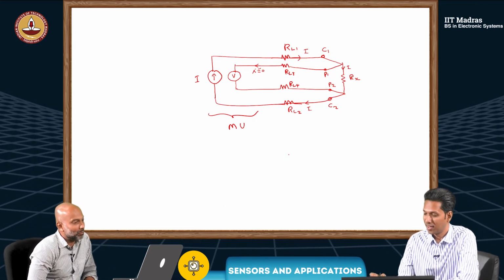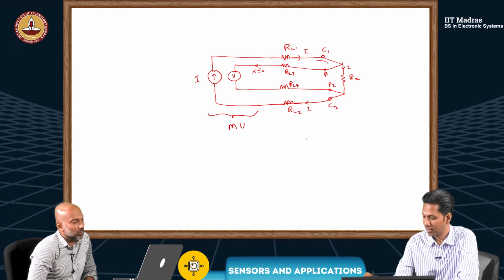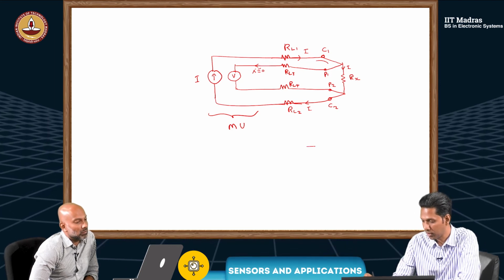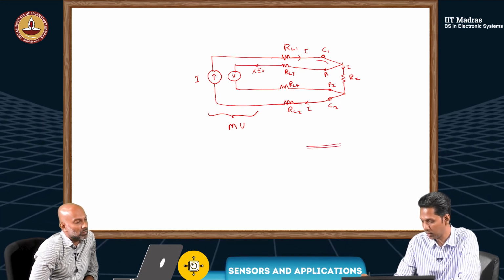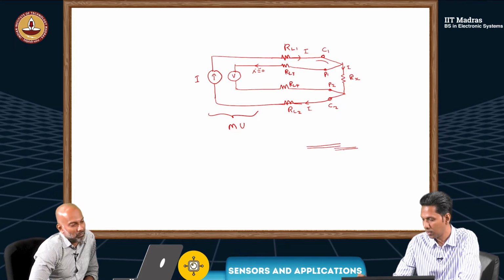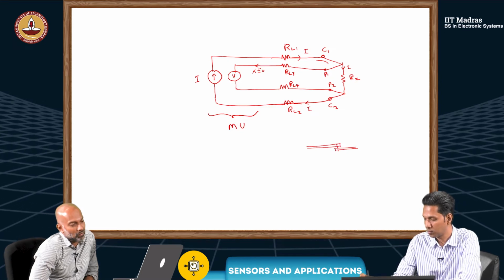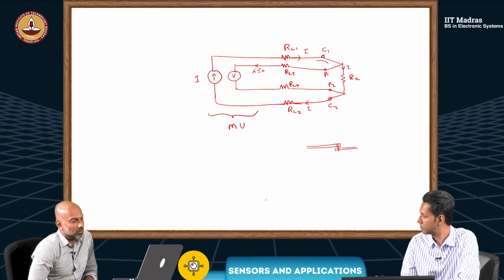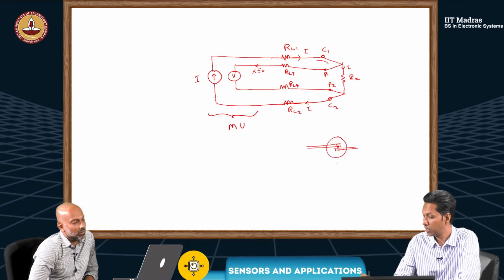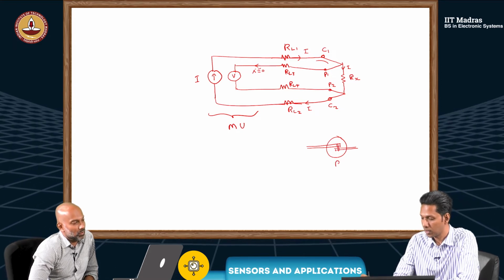So one thing, maybe I can elaborate on this C1, or maybe a better view. See, there is a contact there. So you have some wire coming like this, and then you are connecting this RTD wire there, and these are somehow connected. So when you do this, definitely there will be some contact resistance, let's say RC.